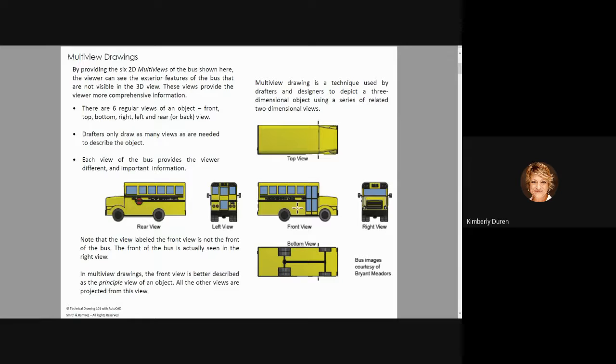So from the primary, how many views can we get? I got my primary. I can get 4 views directly projected. And then, so there are 4 views across the primary. That's 5. And then from one of these, either the left or right projection of the primary view, I have the backside of the primary view.